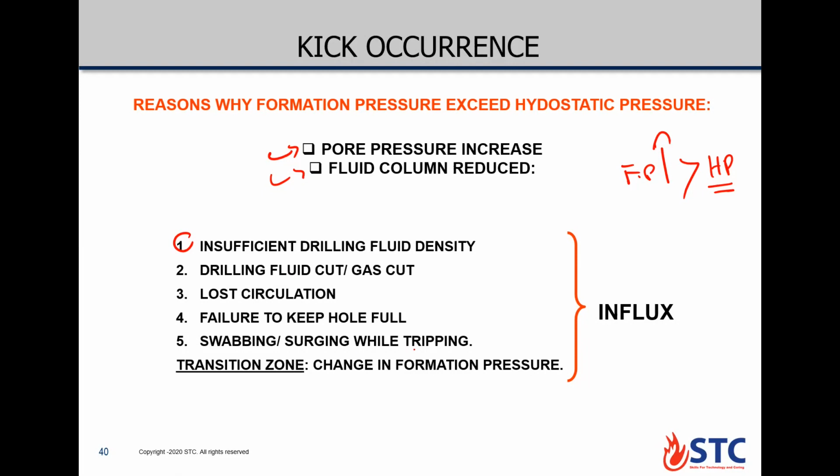Also, if we line up the water tank, we dilute the current mud weight, for example from 10 ppg to about 9.5, so you'll be in an underbalance situation and you may have a kick.